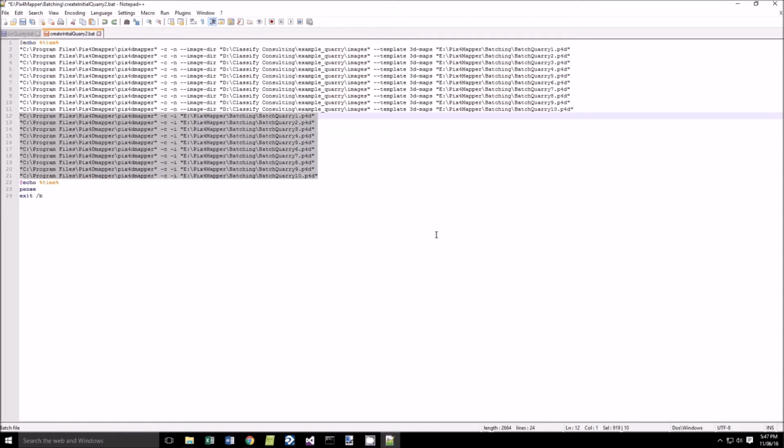This is handy so the processing stops at the point where you can check your quality report and or do your ground control point marking in your photographs. If you don't want or need to do those, you could just change these -i's to -r's, and the entire process will proceed through initialization, densification, and orthomosaic generation.